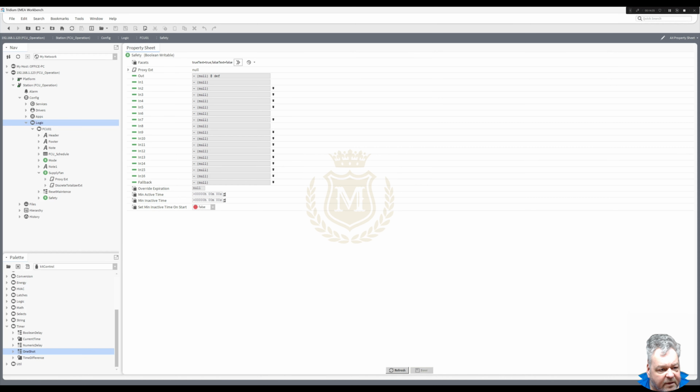Let's put in no fire, healthy. We'll record it safety, so we'll put in fault, exclamation mark, instead of no fire, because we just called it safety. We'll put the fallback in as true at the moment. Let's put it healthy as a fallback.